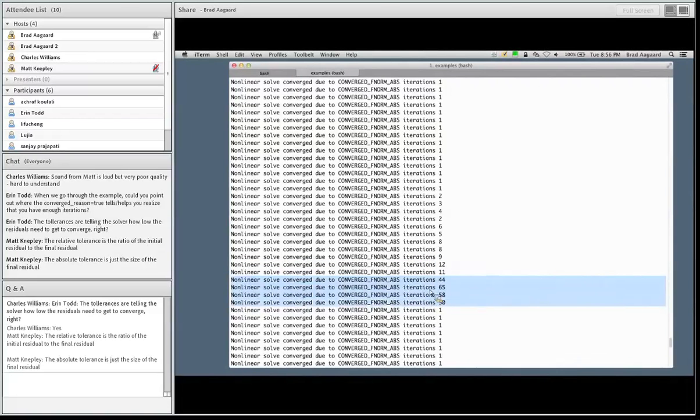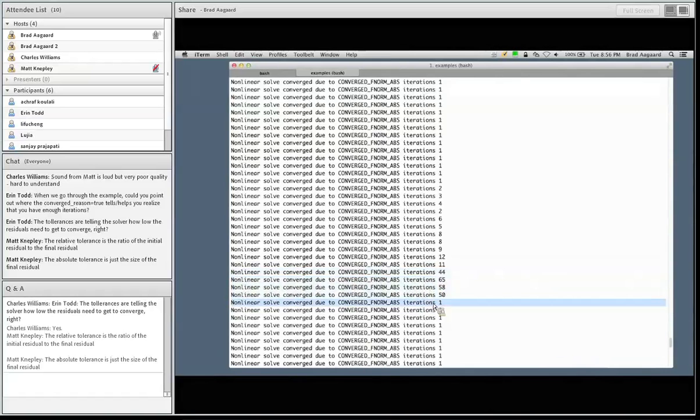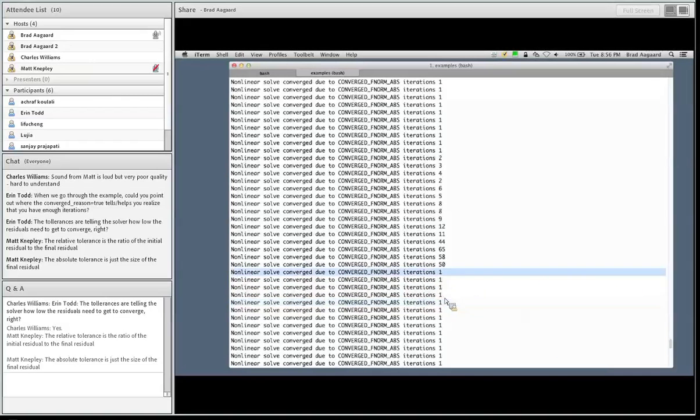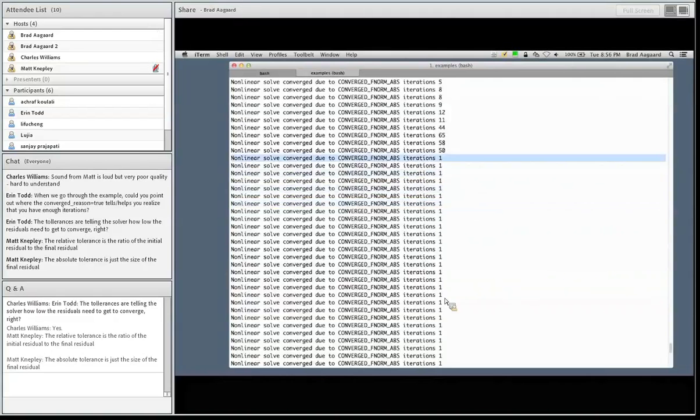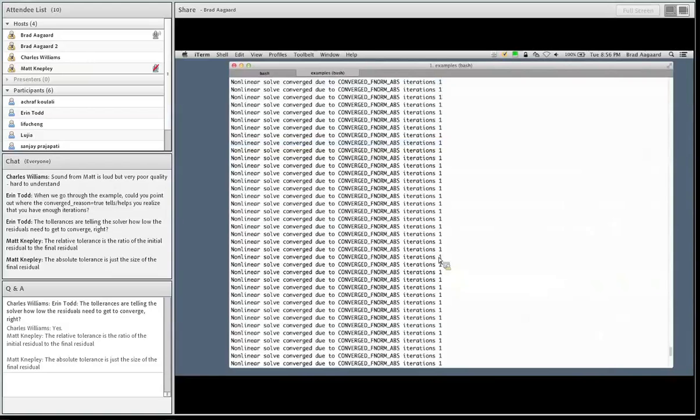And so there are a few time steps where the fault was slipping, and then it locked back up again. And so when the entire fault locked back up, then we're back down to 1 iteration, because when we solved our linear system, the Lagrange multipliers were consistent with our fault constitutive model. And so now we're back to 1 iteration for a bunch of time steps. Now we're getting some more stick-slip behavior, so we get the thing nucleating again. That one takes 10, and we're back to 4. Then we're back to sort of most of the fault slipping. Then just a little piece of the fault is slipping, and then we lock back up again.